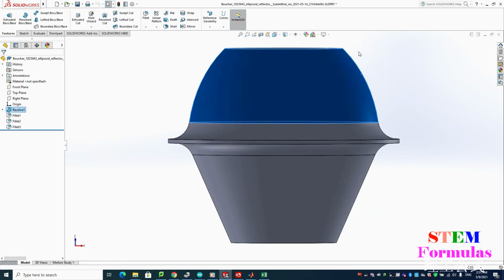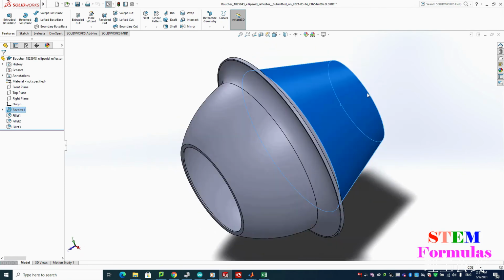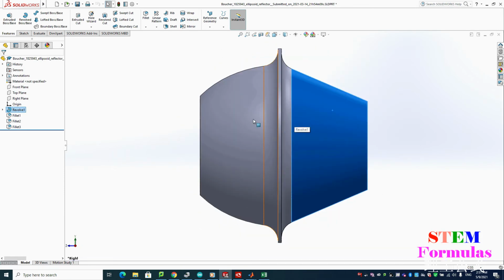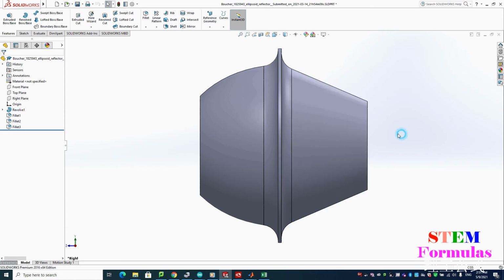So it's always equal and all around. I put a slight fillet here that will help the structural integrity of that lip, because if it's all flimsy, it may break, and you don't want that. All right, so that's pretty much it.